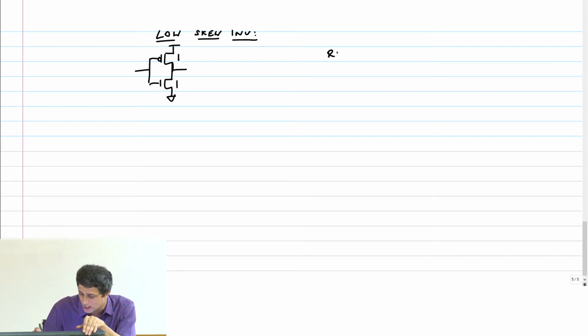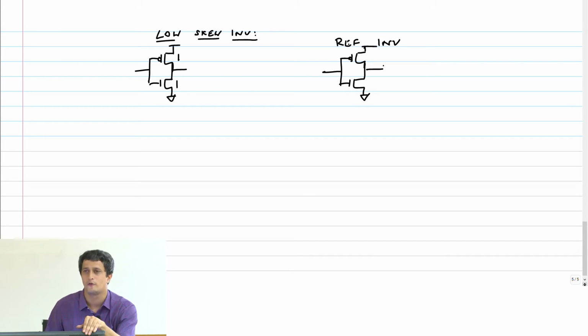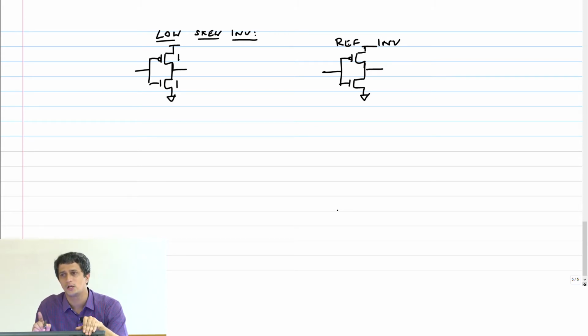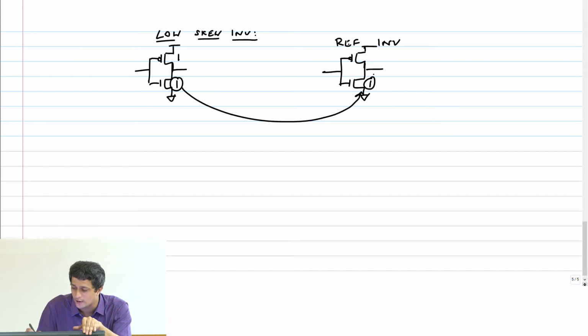We first constructed the reference inverter. And how did we construct that? Let's say I wanted to do it for pull down. I needed to construct the reference inverter such that the NMOS transistor had the same drive strength. So I said you can put this here, right? And therefore this will give you 2. And then we calculated the logical effort, right? But this is equivalent to saying that the current to this guy is actually I.